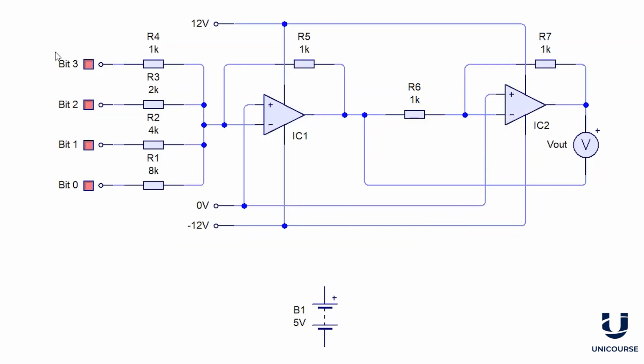So we're going to look at a circuit simulation. This one's going to be a digital to analog conversion. So before we put the simulator on, let's see what's happening. We've got this basically 3-bit, but there's actually 4 input signals. So if we feed either a 0 or a 1 into each one of these at different times, this will then be converted through these 2 op amps to this voltage output. So let's switch on the simulator. Let's start with the first one here.